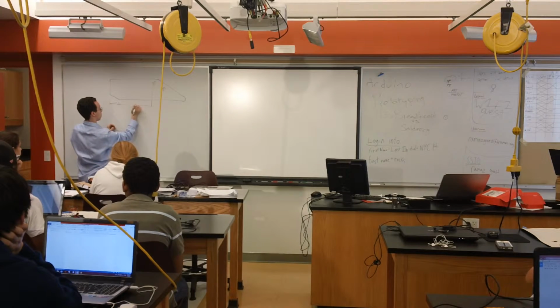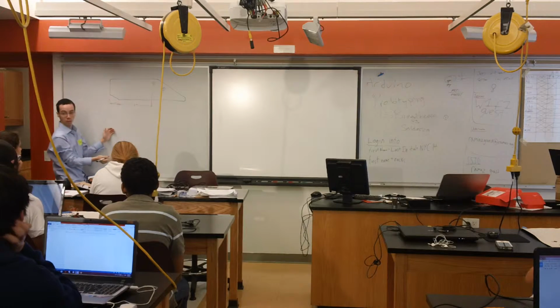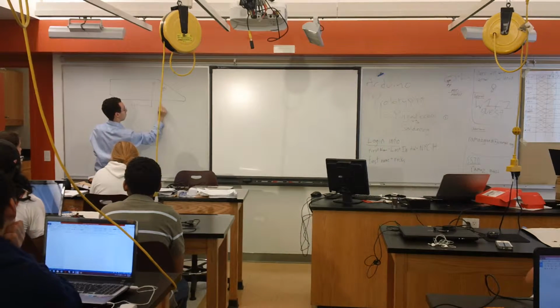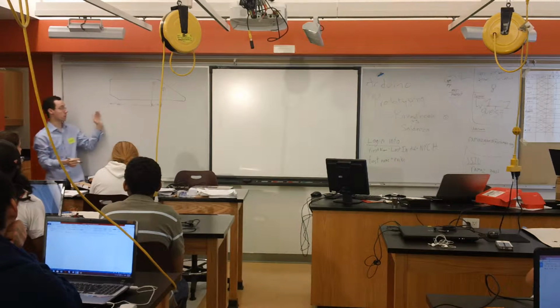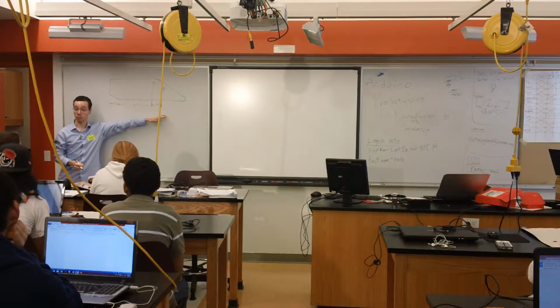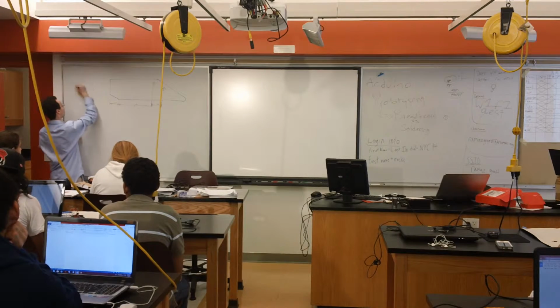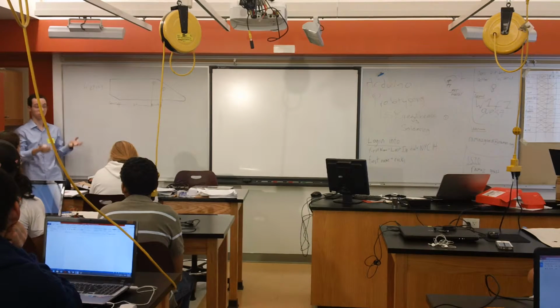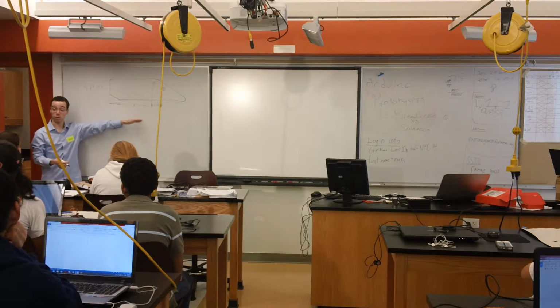Now I say, okay, this one is like 3 inches away, and then from here, this one is a further 1 inch, and so on and so forth until I'm done dimensioning my part. That's called chain dimensioning because the dimensions are like links in a chain.